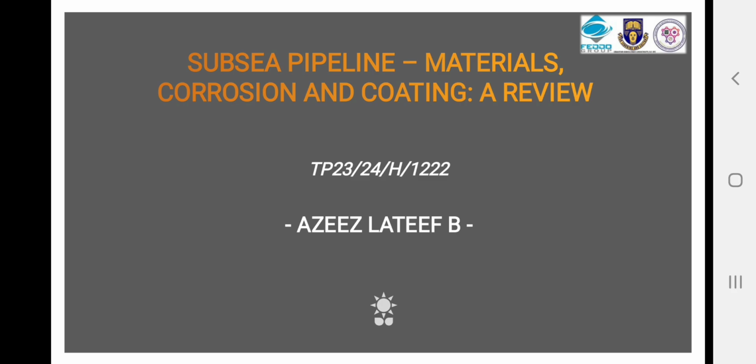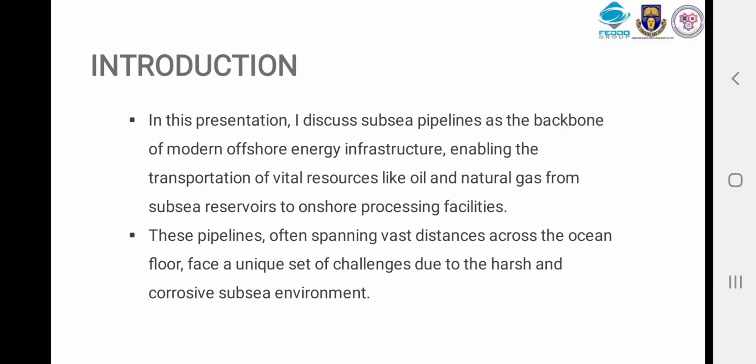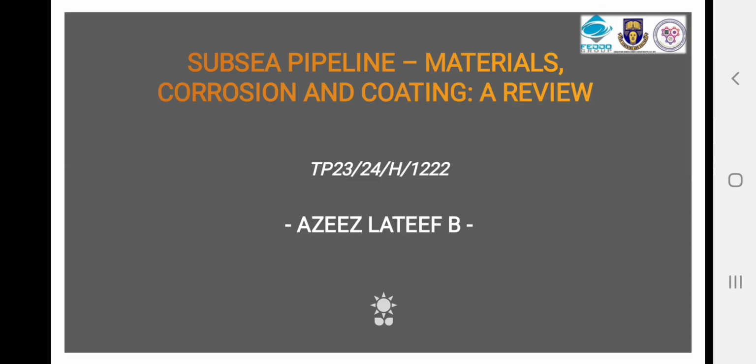This topic also looks into the different mechanisms of corrosion formation in pipelines, and how we can monitor them, inspect them, and correct them using different mechanisms. And also coating as a means by which we can bridge the direct interaction between the materials and the environment. In this way, this reduces the rate at which corrosion will occur in a material.